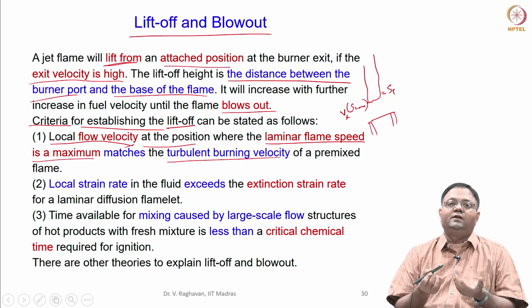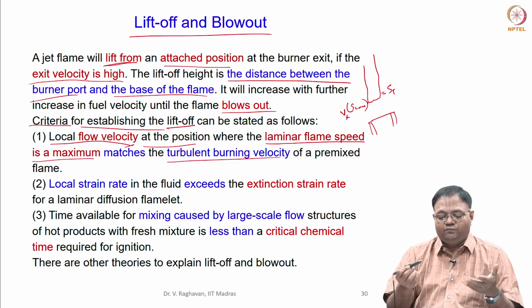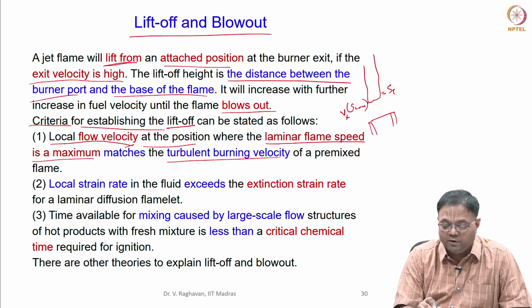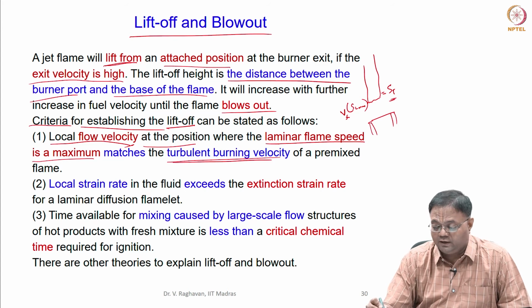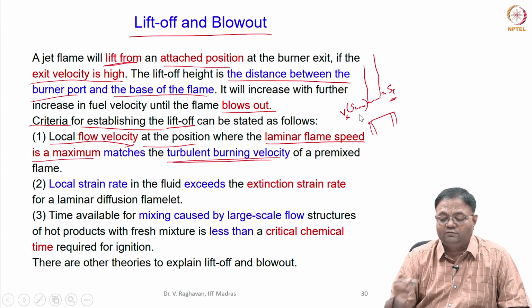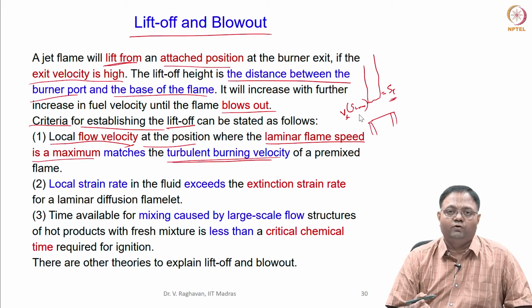So there we can say liftoff, but this is actually complicated, correct. This is one of the theories. If we can come up with some theory or empirical correlations to get the turbulent burning velocity ST, and see the velocity where the maximum SL will occur, then if you can match this, that will be the liftoff location.